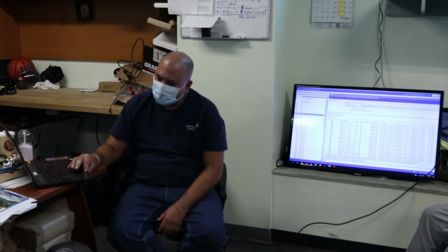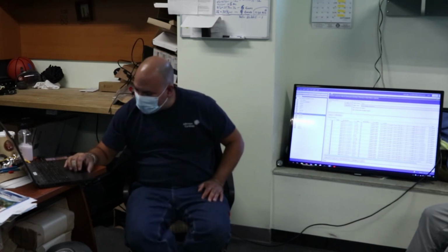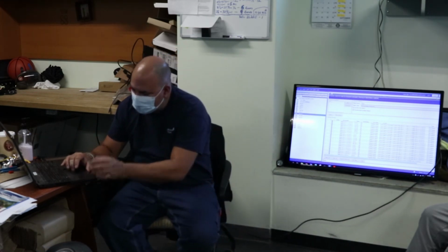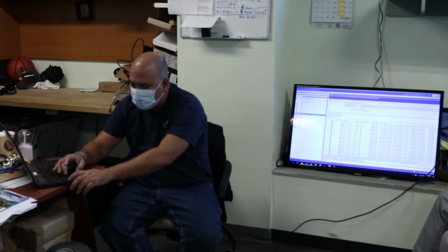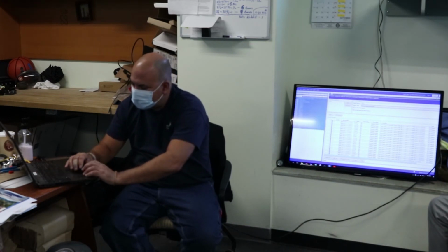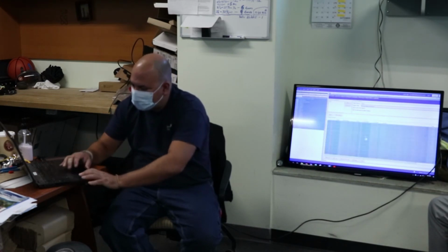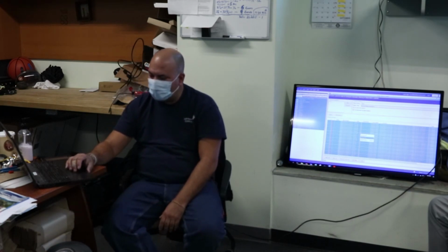So, I mean, that's a good tool. With the heating valves, suppose you wanted to put a load on your system and open up all the heating valves, you could do this here, and then you could, again, Control A, and select them all, and you could override them all, open and close right from here.